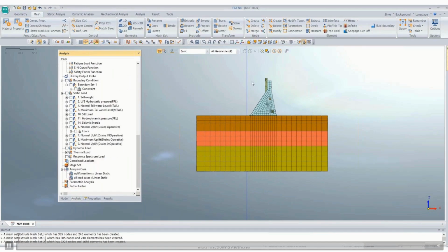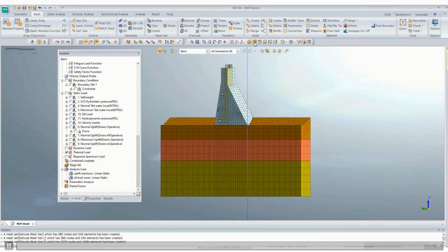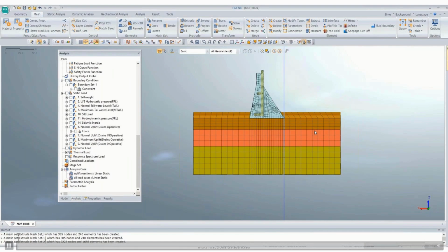I'll be applying this ground motion time history from upstream to downstream. I'm analyzing this dam block for upstream to downstream forces. A seismic wave dissipates at some distance from the epicenter; it doesn't continue through the entire Earth. The entire Earth doesn't shake. If an earthquake occurs in, say, India, America would not shake. So it will dissipate, and we can't model the entire Earth.